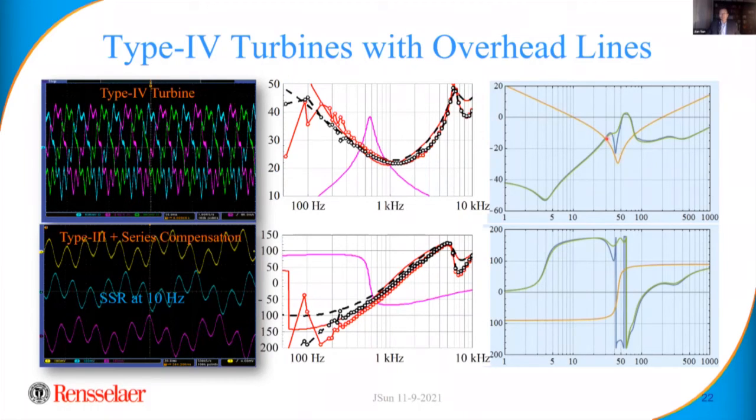Again, based on frequency response, look at the phase margin at the intersection frequency. If the magnitudes intersect at a certain frequency, like here 20 hertz, right? And you look at the phase difference at that frequency and it is larger than 180 degrees, this indicates unstable resonance. The equal magnitude indicates a series resonance, because on one side you have a capacitive impedance, right? The magnitude drops with frequency.